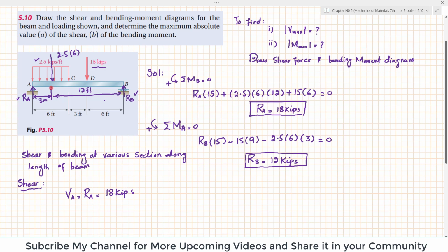Clear? Now at point C, the shear force will be equal to 18, because 18 is over there, minus this distributed load. This distributed load will be converted into a concentrated load. So 2.5 times 6 feet. When you calculate this, VC will be equal to 3 kips.